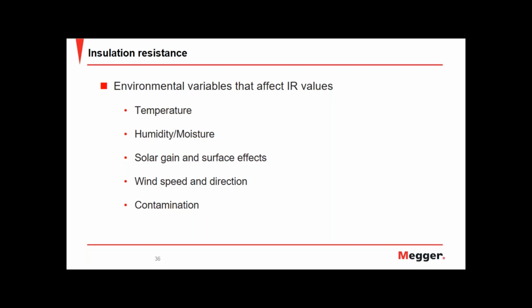In assets such as coil windings found in motors or on HV bushings, the surface of the insulation presents quite a large area on which contamination can land and build. Contamination can occur naturally due to airborne pollutants such as dust. It could be salt from the air in a salty environment, where we are here in Dover. We're very close to the sea. It could be diesel particulates from vehicles. These all add up to contaminate the surface of an asset.